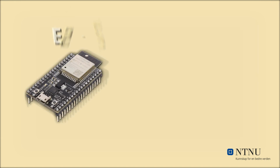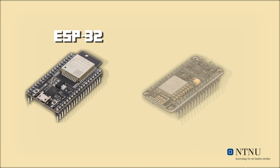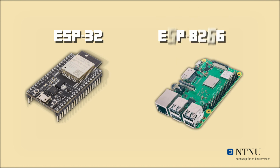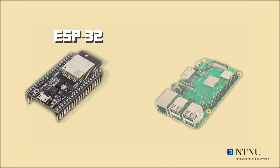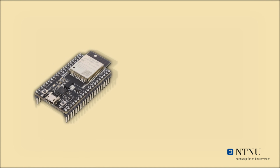The ESP32 microcontroller was chosen as the uplink node because of the performance advantage at a low price compared to similar microcontrollers. Other considerations include the ESP8266 and similar performing boards, but we found the added core on the ESP32 such an advantage in offloading the Wi-Fi workload that we prioritized it. The more powerful Raspberry Pi 3B Plus model was also considered, giving a huge performance overhead, but was concluded to be unnecessarily powerful for our system. At a very high increase in price, we could not justify it if low cost was to be a selling point.